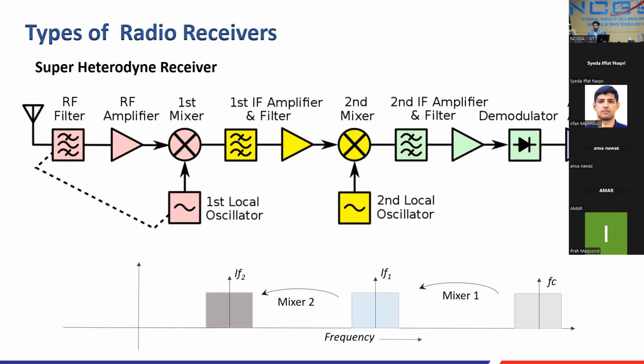In a receiver chain, the second stage mixing is usually to bring the signal back to a sampleable standard where you can actually sample it. Every system might have different ADC requirements and different data rate requirements. Let's assume that your IF signal is centered around 3090 megahertz. Then putting in a high speed ADC at 1300 MSPS, you will need extra effort at the digital end to handle that data.